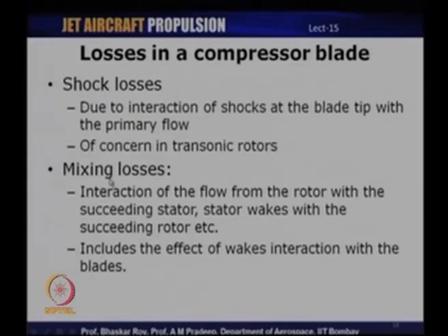And the last form of losses are known as mixing losses, basically because of interaction of the flow from rotor with the stator, or the stator wakes with the succeeding rotor, and so on. So, it is basically the effect of or interaction of the wakes which are as a result of the rotor or the stator interacting with the subsequent stage. So, mixing losses basically pertain to interaction of these wakes with the subsequent stages. So, all these losses put together, or sum total of all these losses, are equal to the total loss that are incurred in a compressor stage.